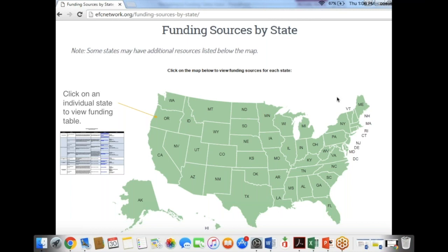But here's the kicker. Every time in New Zealand for the last 3 cycles that we've renewed the discharge permits, the conditions have changed. This is environmental discharge conditions. And the minute they change, you've got different process trains. So what I've been saying to many of my clients is, look, the life of your assets is actually the life of the permit. Because if you completely change the process to meet the new environmental requirements, you're going to abandon those assets.